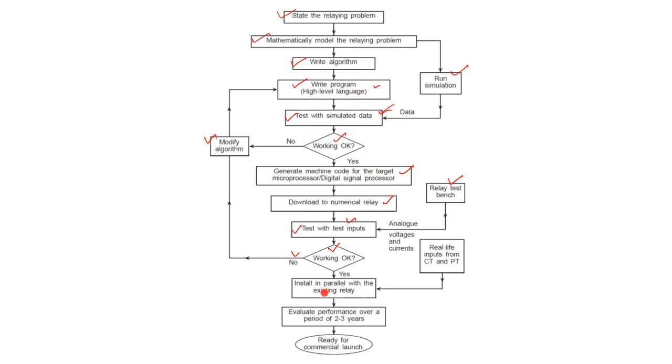If it is yes, then we have to install it in parallel with the existing relay, and feed the real life inputs from CT and PT to the relay. Then the performance of this kind of relay is evaluated over a period of 2-3 years. After that it is ready for commercial launch.